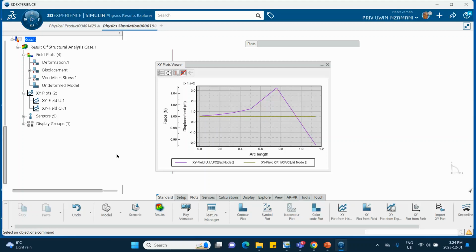And at that point, the YouTuber says, wait a minute, this doesn't look right because I ran it earlier today and it was different. So he says, I think the problem is in the arc length value that I specified. There is one thing that's bothering me here. Oh yeah, okay, you can see that during that RIKS step, the load to the right is 1 Newton. We know that. It comes from step 1, which was 1 Newton, and it stays like that.